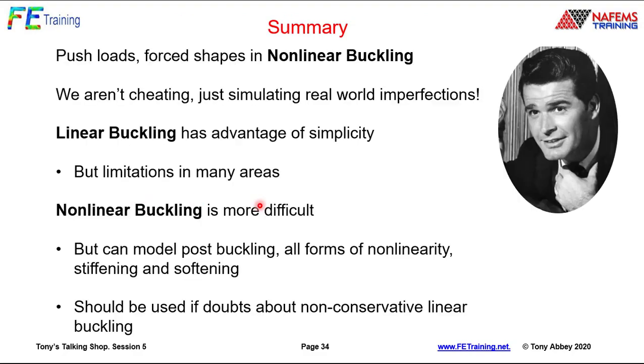So in summary, the push loads and force shapes that we used in nonlinear buckling, honest, this is Jim Garner again, we weren't cheating, we're just really simulating real world imperfections in the best way we possibly can. Now linear buckling, we don't need to cheat. It has the advantage of simplicity, but has limitations we've seen in many areas. It is small displacement, there's no stress stiffening, there's no geometric nonlinearity in it, so it has limitations, and the biggest limitation is if we've got something which is not a slender structure, it's over predicting the load level which is going to buckle.